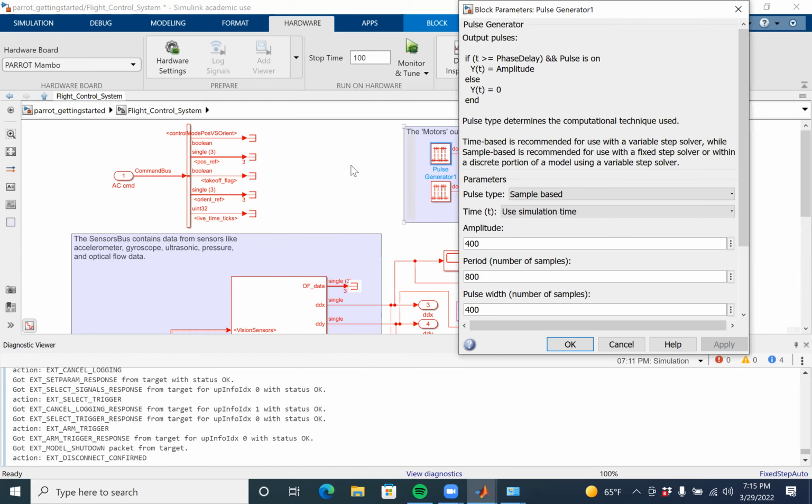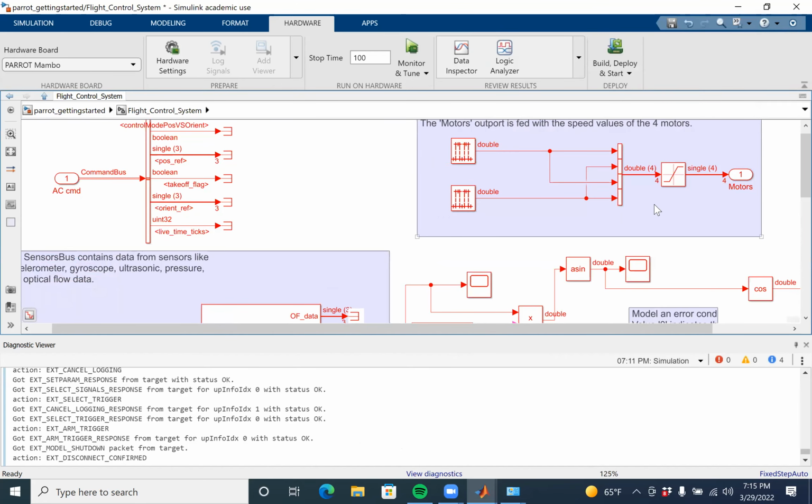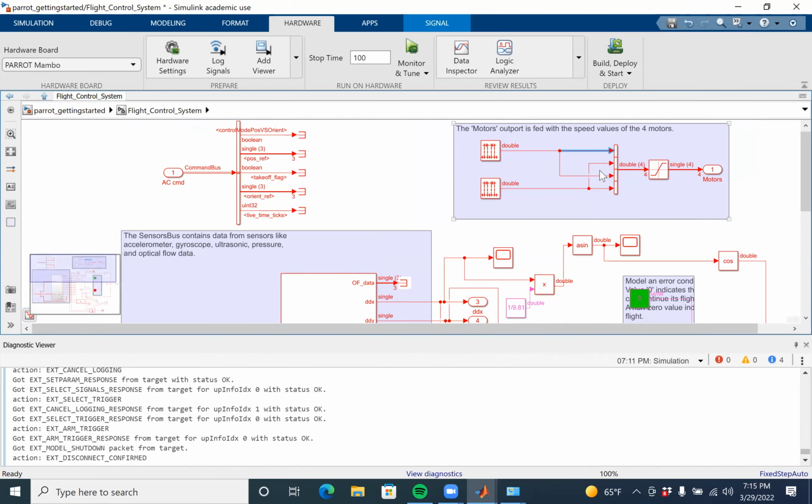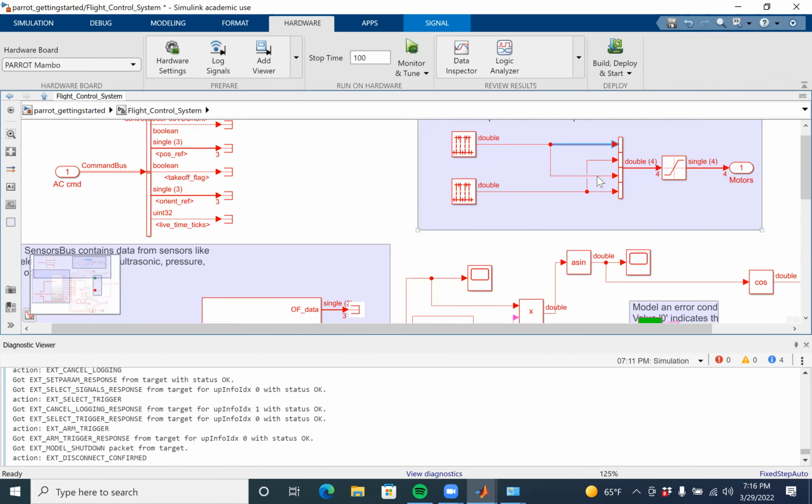Last part. So this is the motor mixing algorithm. What is this motor mixing algorithm? This is the input to motor 1. It's a controller for PWM. So what you will do is adjust the PWM, and that will change the speed of the motors. And that change of PWM will be dependent on the error. So the pitch multiplied by a constant, you will map it to PWM.